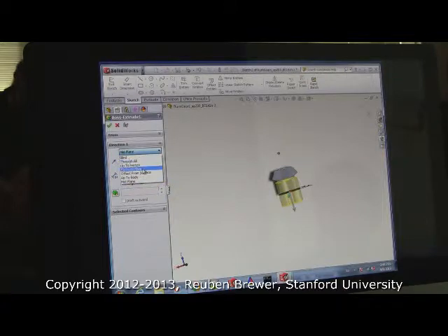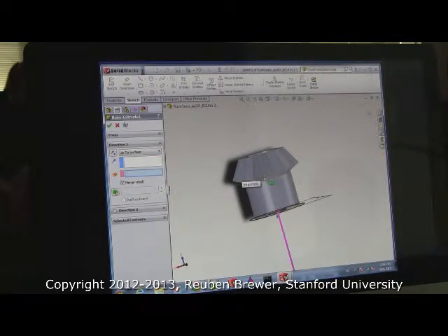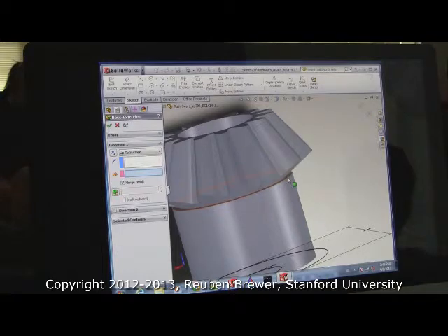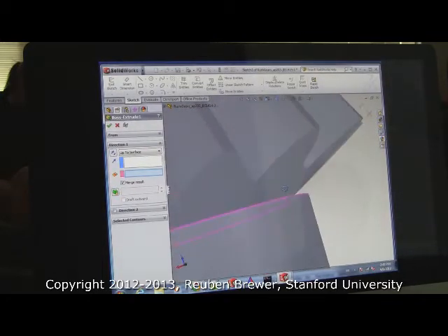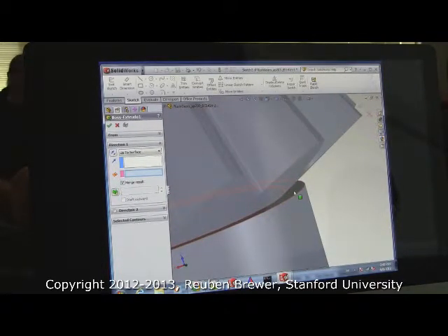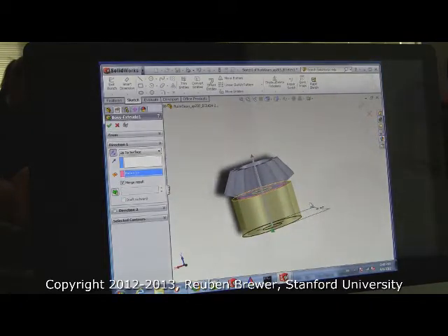We're actually going to do up to surface, okay? So hit up to surface, and basically it's going to extrude until we hit the surface that I pick. Zoom in right here. See this lip on my gear? And select that. Now you see how it extrudes to that surface? Has everybody got on their screen what I got on mine? Again, if you can't find the surface, just zoom in. It's really hard to click these things.